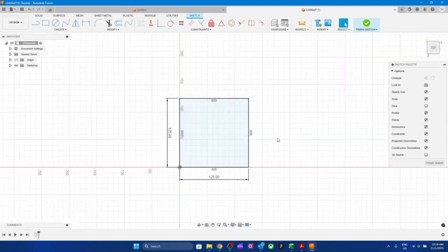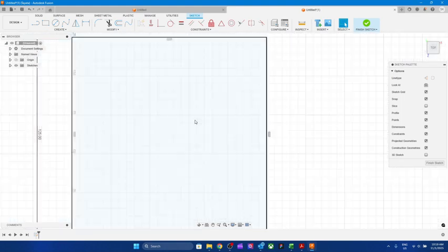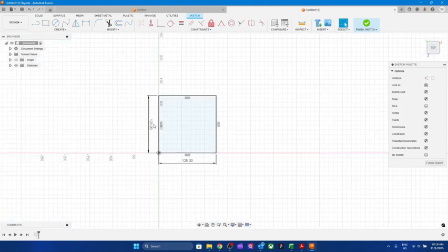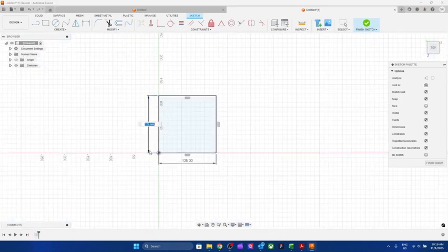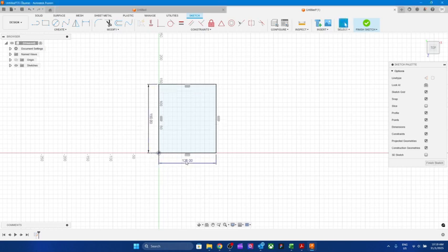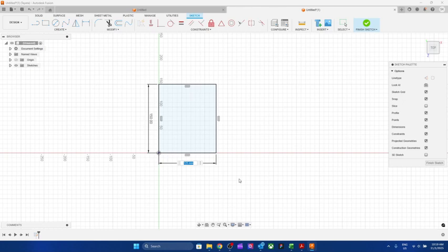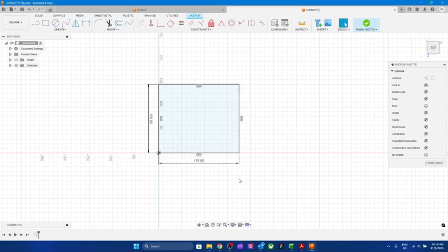You can zoom in, zoom out. You might be able to change the dimension. If I decide that no, it's not 125, it's 150, I'll simply click 150. Oh no, it's not 125, it's 175, so I'll change 120 to 75. Can you see? So now this will not move anywhere, it's fixed, whatever you do. And this is called a fully constrained sketch in SolidWorks. Okay, this is fully constrained.